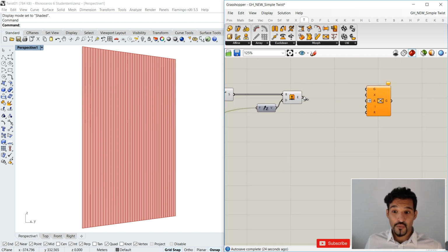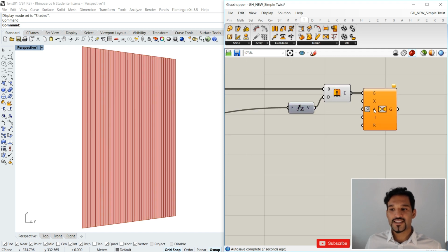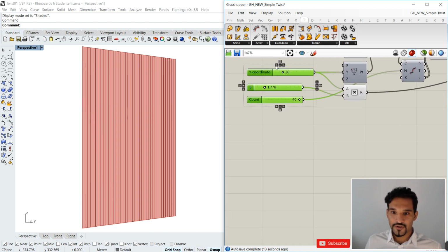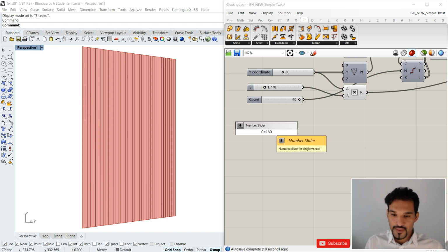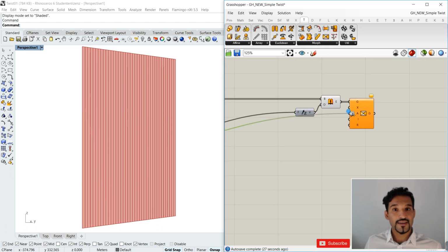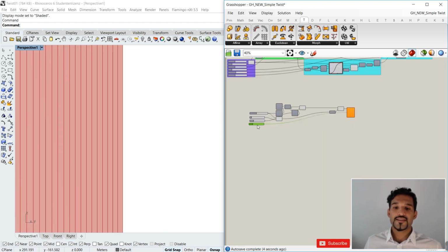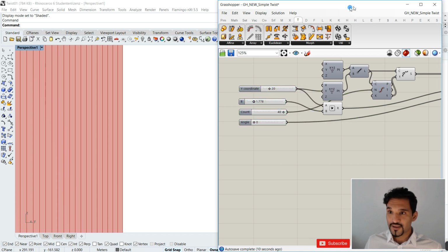Okay, so now we have one step done. We can supply our basic shapes here. So we are one step closer. And now the next thing that we want to do is actually just hook up our angle, because that's quite straightforward. So I will again create, here in our control panel, a slider saying 0 smaller 180. 180, of course, in this case, a full half rotation. And I'm just going to put the slider into the designated input, which is the A with the degrees. And the nice thing about our sliders, of course, is that they will get the annotation automatically.